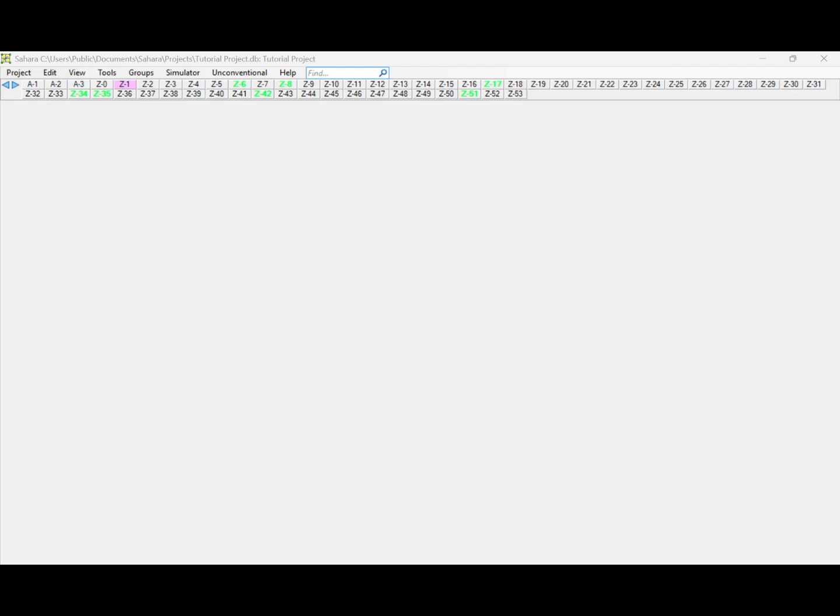Verify that your wells have the correct status, that the wells are updated from producers to injectors when you do a conversion, and that they have the status correctly defined. Also verify the status of the layers, whether they are correctly open or closed before starting. Always check that the map reflects this precisely.